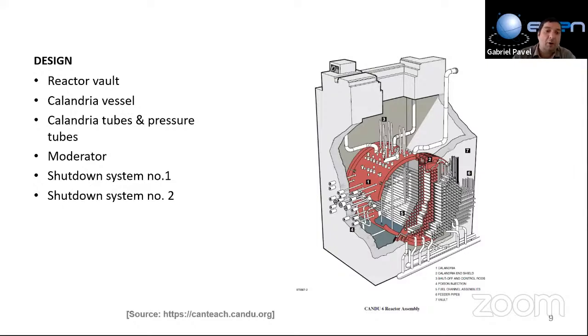The normal operating temperature of the inlet header is about 260 degrees, 266 more precisely. The outlet, after the water was heated, is about 316 degrees. And let's say the operating pressure is about 10 megapascals. The coolant flows at about 24 kilograms per second, if I'm not wrong.